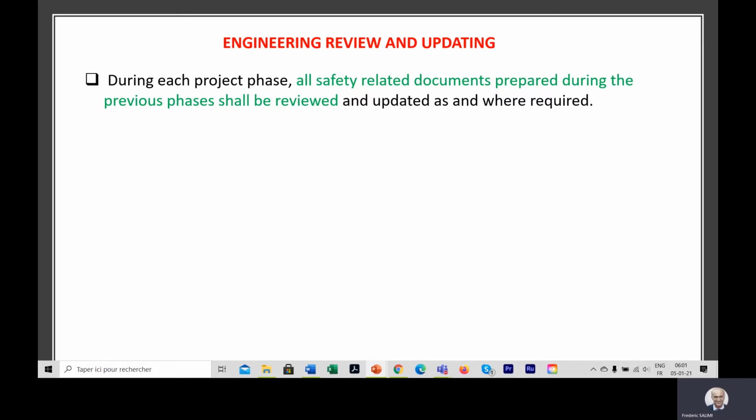This safety concept shall be updated in detailed design when the layout plot plan changes, and it should be issued at an earlier stage of the EPC phase, because this is a document that holds the decisions of the project about the active protection, passive protection, everything. It should be updated, and the project follows the instructions given in the safety concept.